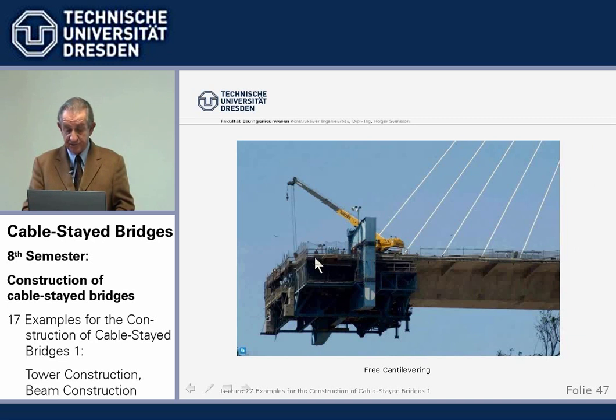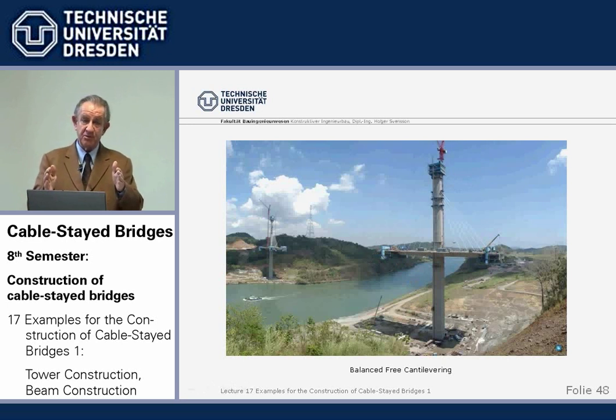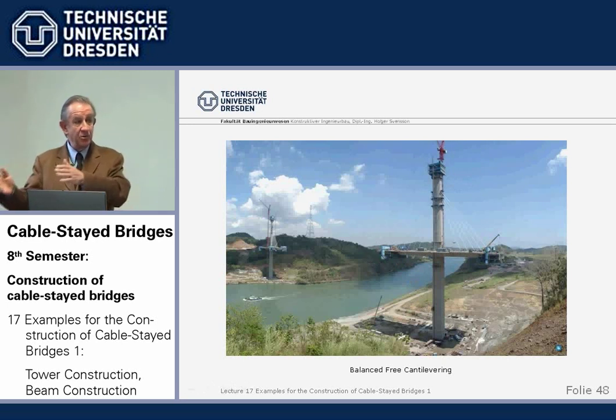And this is the short form, again 4.5 meters deep for 6 meters. There the beam can carry that itself, so we don't need any auxiliary. We see here free cantilevering parallel to both sides. Again, because of the short lengths of the elements, we had little weight left or right out of balance. So the moment about the tower was fairly small, and we didn't need any auxiliary staying of the tower.